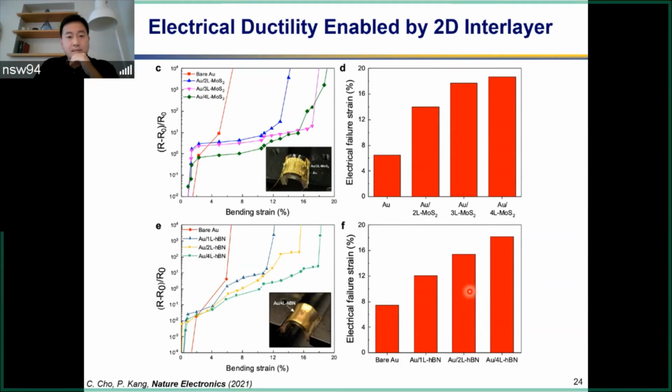So it turns out this fracture surface is actually exhibited in MoS2 and hBN. This is a semiconductor. This is an insulator. So of course, there are differences. It turns out graphene is most effective of the 3, but nonetheless, this fracture behavior, this kind of stable resistance behavior still persists in different 2D materials that allow this buckle formation and guide the crack formation, and of course its own intrinsic strength when it comes to stretching of the 2D material.